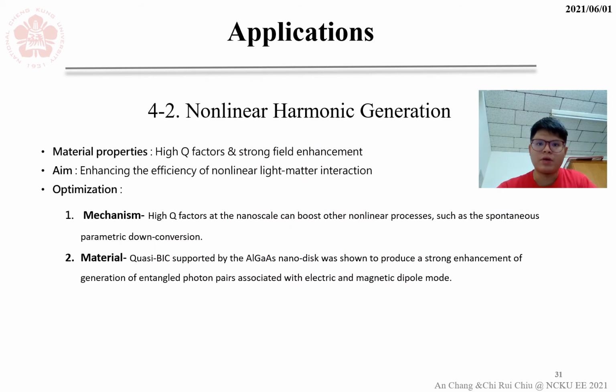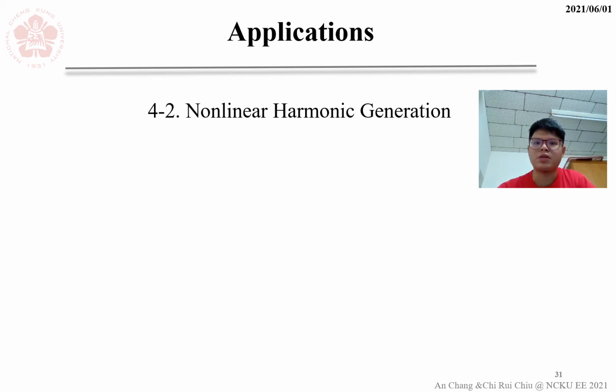A structure composed of a silicon nanodisk. This system is able to sustain the anapole state. We get a result where it generates a conversion efficiency 1 order of magnitude higher than that observed for third harmonic generation at 500 nanometers. The second is placing a silicon nanodisk on top of a gold reflector. Using the characteristic that metal has free charge oscillations at the interface, we get a result where the highest THG conversion efficiency of 0.01% was experimentally achieved.